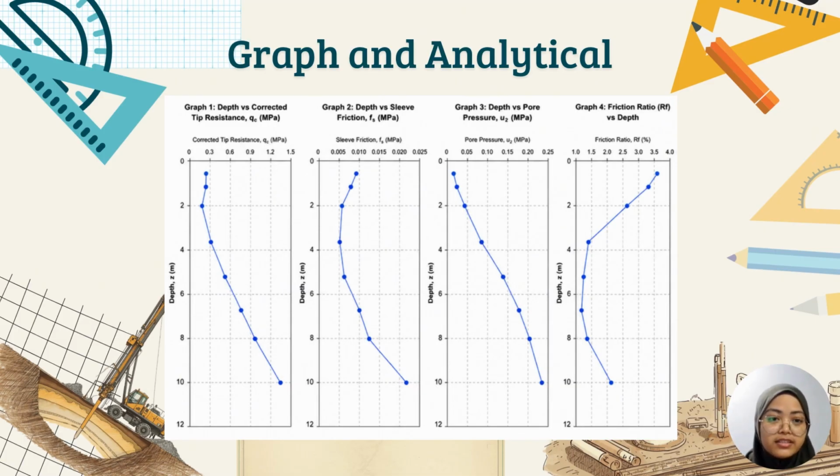Finally, the undrained shear strength was calculated to estimate the shear strength of the clay under undrained conditions. The formula used is Su equals (qt minus sigma v) over Nk, where qt is the corrected cone resistance, sigma v is the total vertical stress, and Nk is the empirical cone factor taken as 15. Substituting the values of 1196 kPa for qt and 137.8 kPa for the total vertical stress gives an undrained shear strength of approximately 70.5 kPa.